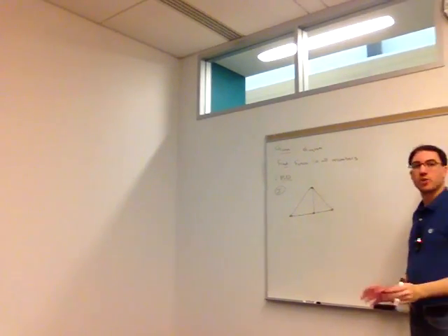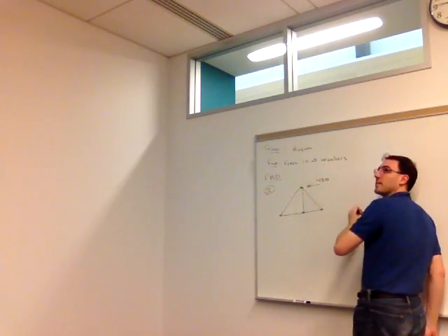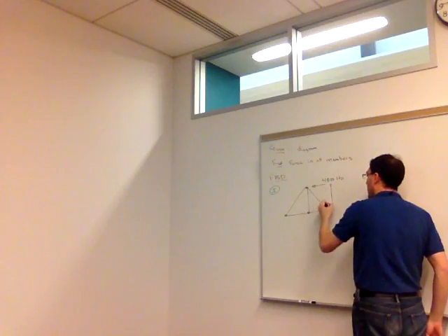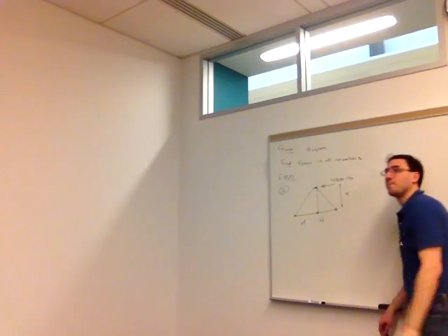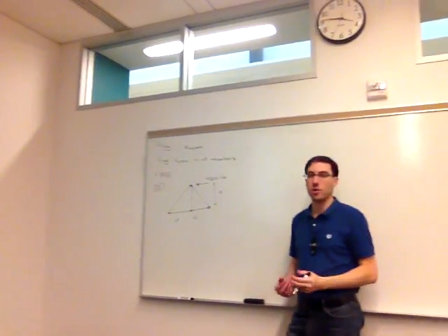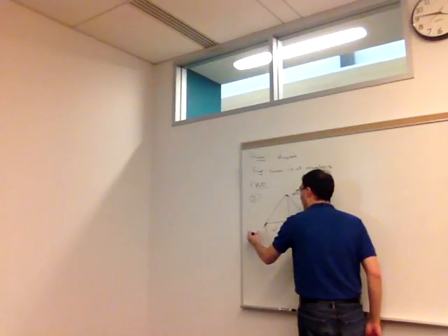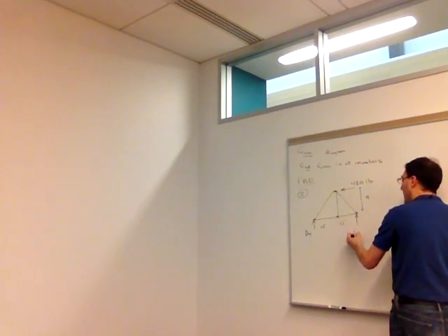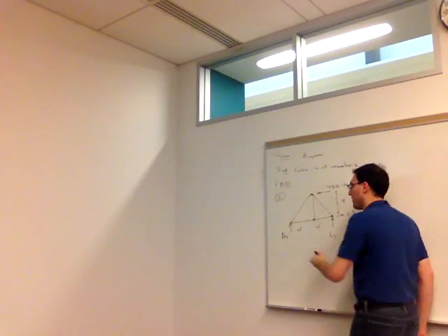Right, so I have my entire truss. I have a 450-pound force acting at point D. And now I'm freeing it from its external supports. So that roller at A, I'm going to replace with that one force I'm going to call AY. And at C, I'll have a CX and a CY I'm going to assume are positive.